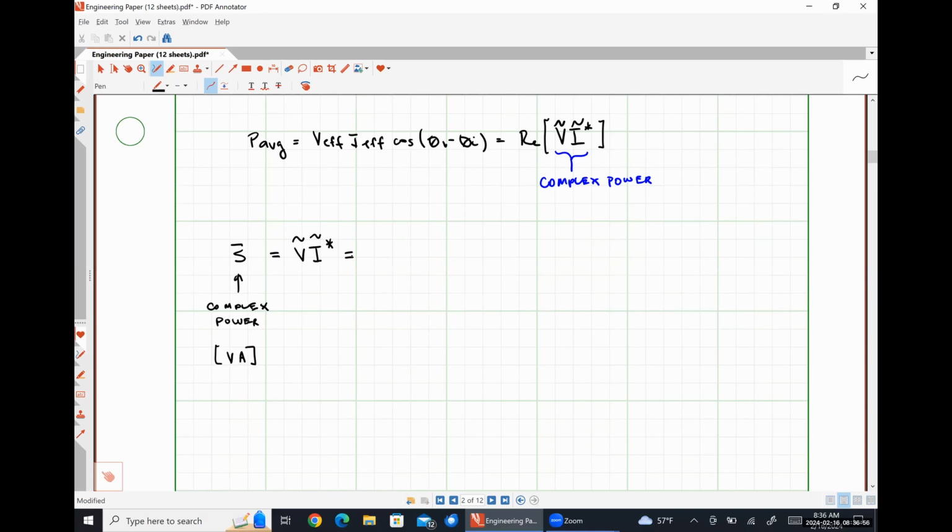So let's deal with the rectangular form first. Yes? Make sure you conjugate the current, but not supposed to multiply that. Correct. So that is the voltage multiplied by the conjugate of the current. If I were conjugating both of them, I would put V and I in parentheses to indicate that both were being conjugated. And we'll work some examples.